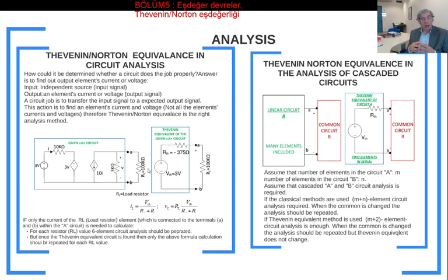So we could answer that question by using the Thevenin equivalent circuit. How have we done it? Here you are. This is the 5-element circuit that we have already examined, and we found the Thevenin equivalent circuit for it, which is this. Now, if I put a load between the terminals A and B, which is that 100 kΩ here, then with the original circuit I am going to find the current and voltage of this load. If I use the Thevenin equivalent circuit, I replace all these elements with just two and put RL here.